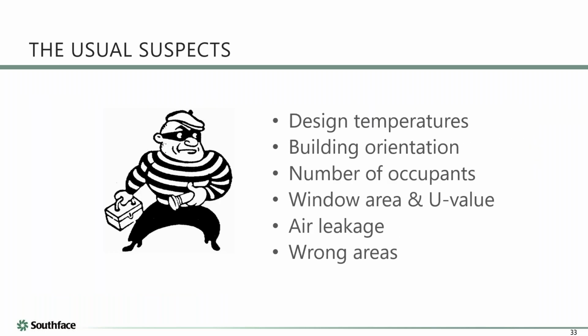So we're going to talk about what we call the usual suspects. One of the advantages of a program like, I'll pitch EarthCraft, is that we require our technical advisors to not only collect the Manual J, but to actually study it and look for problems on it. We train them, and they know enough about load calcs to look for the problem areas and ask, does this pass the straight-face test? I've seen people fudge pretty much everything on this list, and some of it was intentional. So don't mess with the design temperatures, and we'll go down this list.